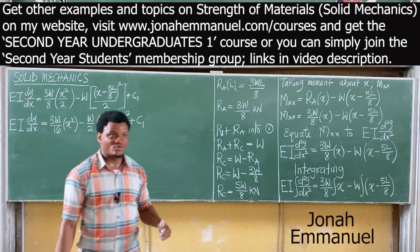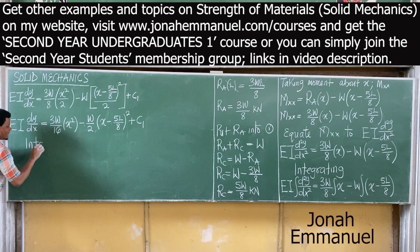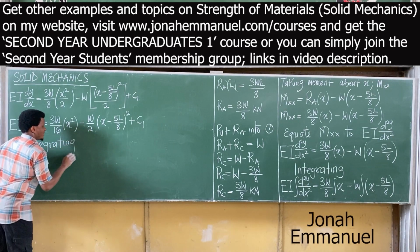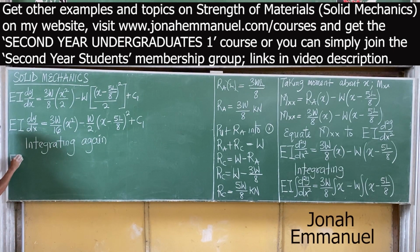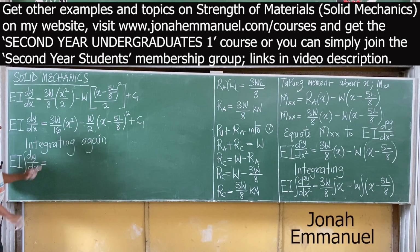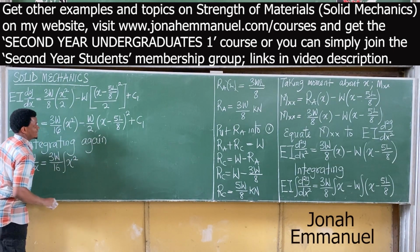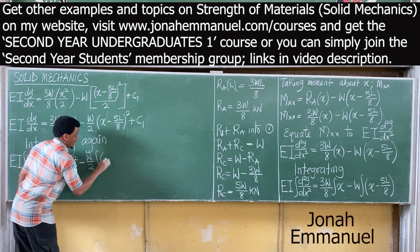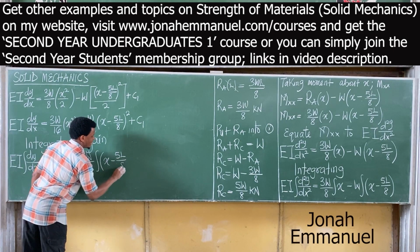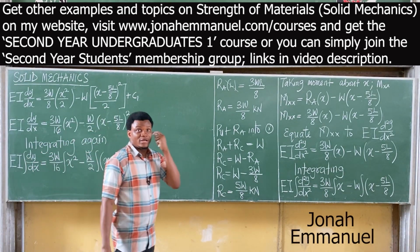What's next? Integrating again. Integrating again, I have EI, the integral of dy/dx, it's equal to, this is outside, 3W over 16, the integral of x squared minus, keep this one outside, W over 2, the integral of x minus 5L over 8 squared plus the integral of C1. Now integrate C1, so I have this.